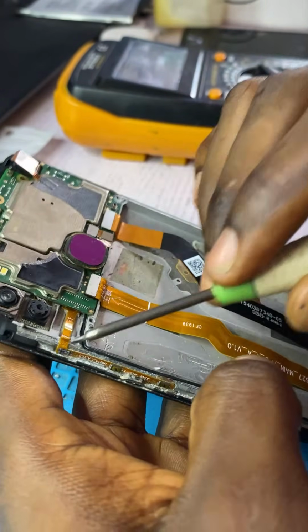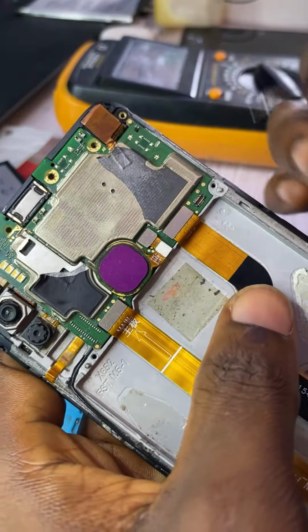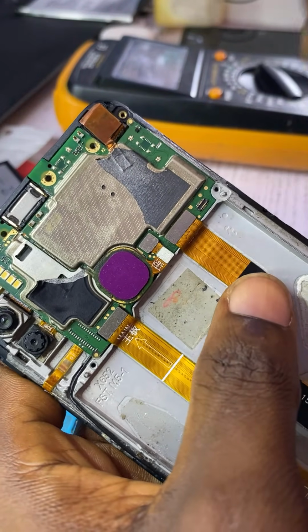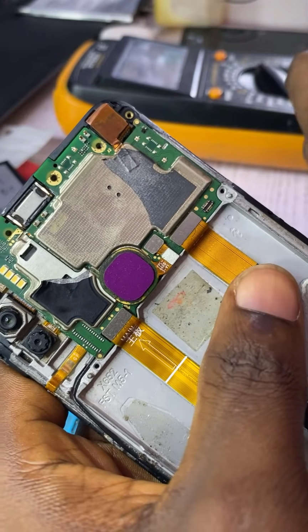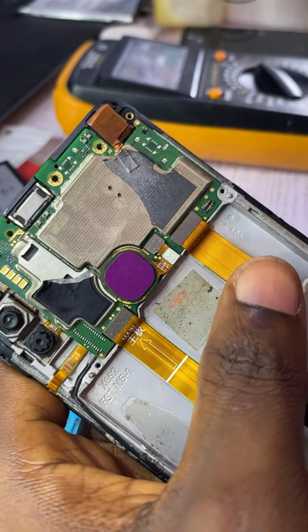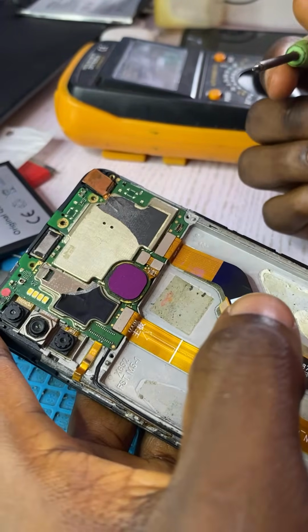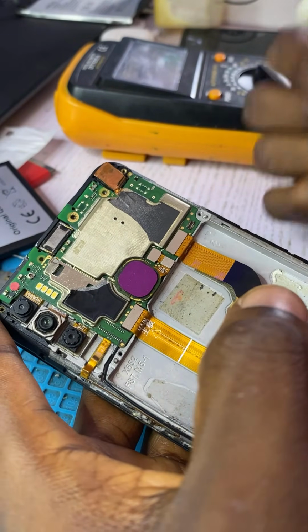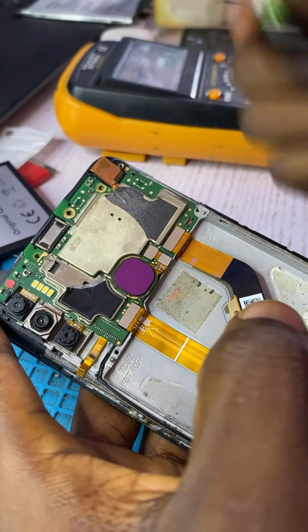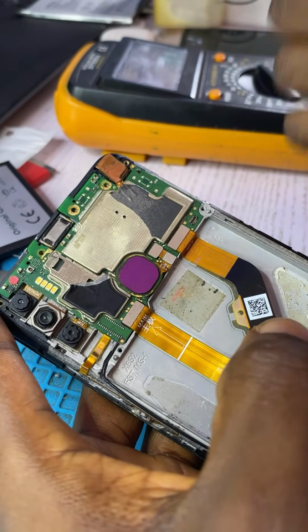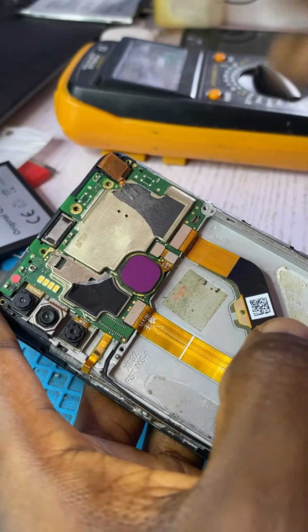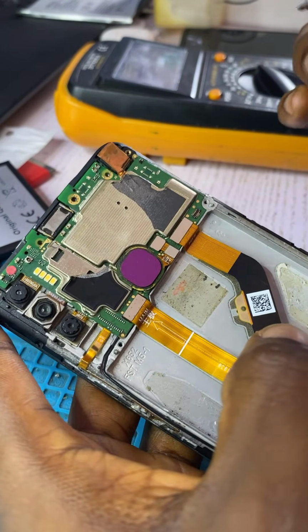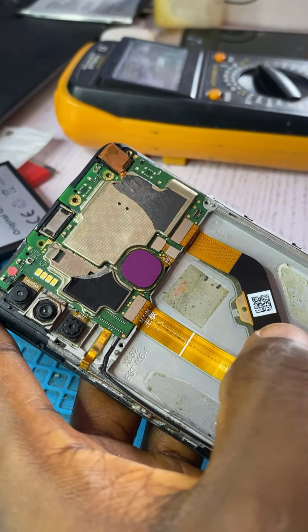First of all, we check the power button. The second step is for us to check the battery. We check the fluctuating power. We check whether it's fluctuating or not, because if it's fluctuating, the phone will be shutting down and turning on, shutting down and turning on on time with that number, okay? So I've confirmed 1, 2, and 3 are not the cause. So I'm going to go to the next point.